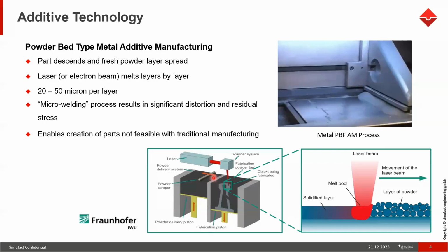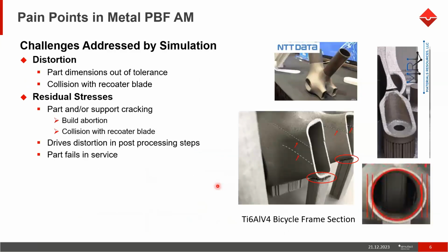Most machines are programmed in such a way that whenever they find there is a chance of recoater jam, the machine will stop and the manufacturing process will halt there. It will not go further. So there is a lot of material wastage. However much material you manufactured, that will go to waste actually. That effect is called recoater collision or recoater jam.